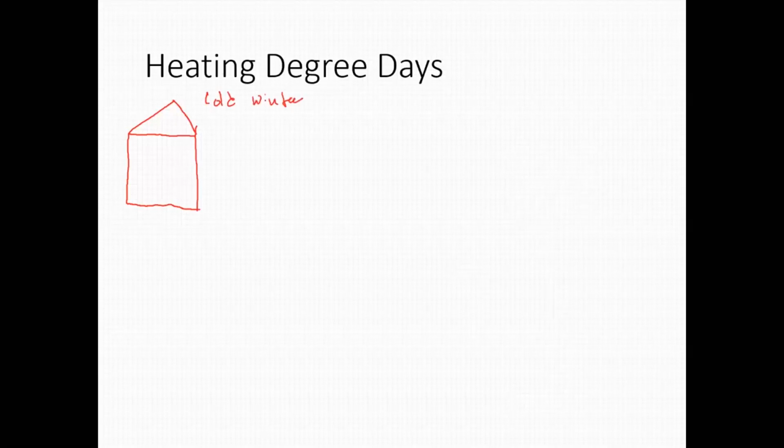Here's your house. You've got a heater in your attic. Hopefully it's in conditioned space. Whenever you guys are designing homes in the future, don't ever put your HVAC system outside of conditioned space unless you've done something to make sure you're not causing undue loads on your HVAC system.